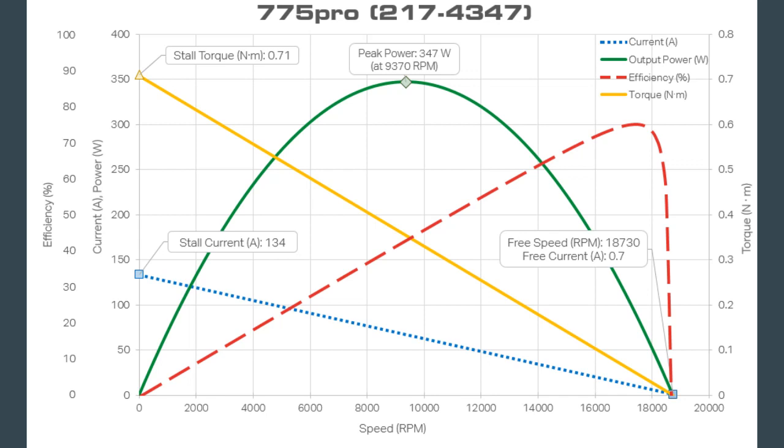Sorry, what did you say before that about 12 volts? You said this chart is for 12 volts, or what were you saying? Oh, I was saying max efficiency, but 18,000 RPM is max efficiency. Yeah. So usually max efficiency is like 8 to 15% stall torque. So usually really low torque is mostly much more efficient.